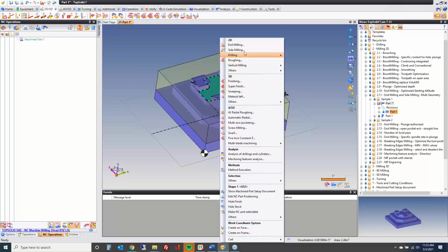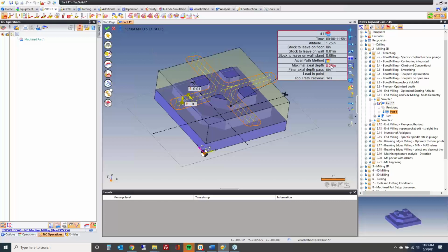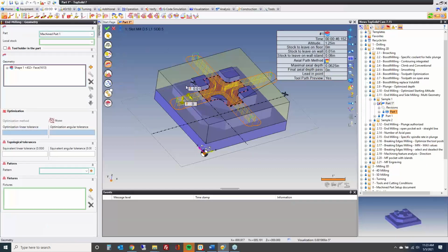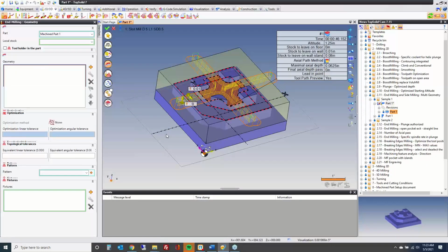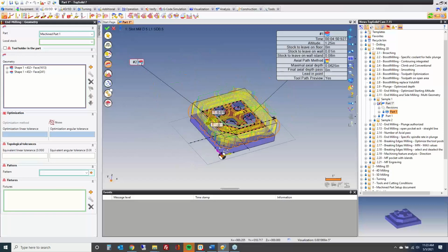So I'm going to go here, go to end milling, like you normally would. And maybe my depth of cut here, maybe I want it to be fine, 1/16 of an inch. Cool. Now, I also want to machine this altitude. But at that altitude, I'm not too concerned about taking a shallow depth of cut necessarily, so maybe I'll do this every 150 thousandths.